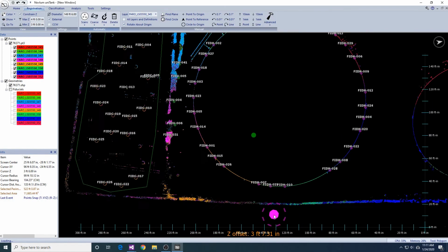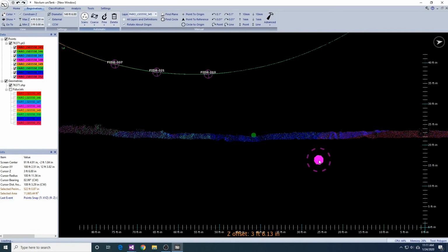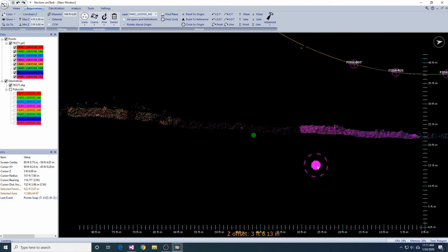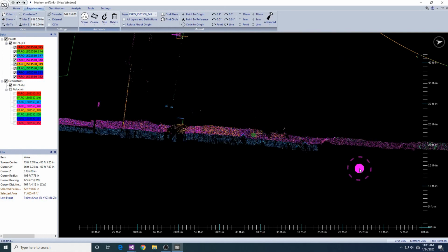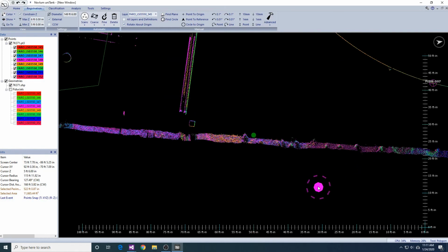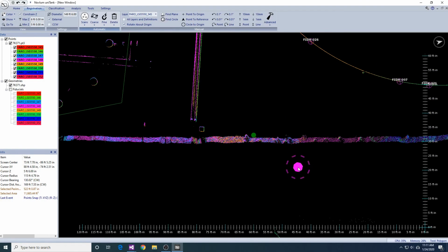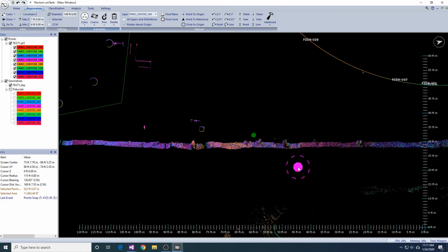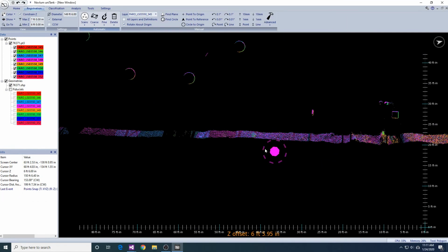If we find that the right side of the registration is still weak, we can use the berm as horizontal control. We typically only use the berm as a last resort because they often are covered in vegetation and are not very steep. However, if we need to use the berm, we can simply place fiducials along the sloping side of the berm. We want to use areas that appear relatively smooth and that have overlap between layers.